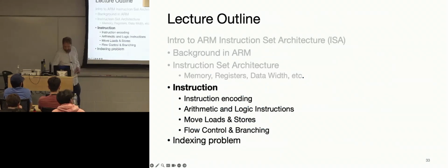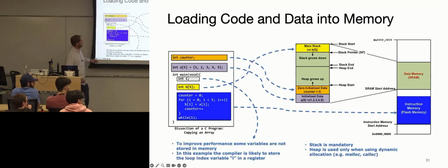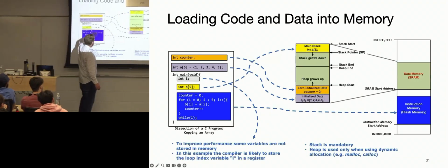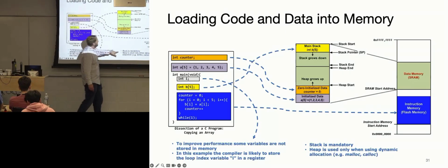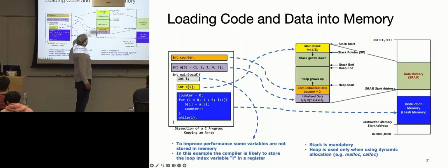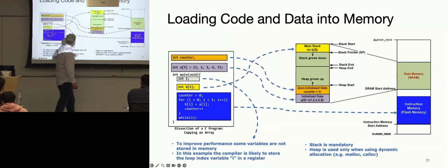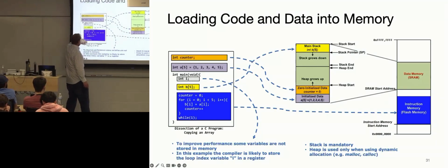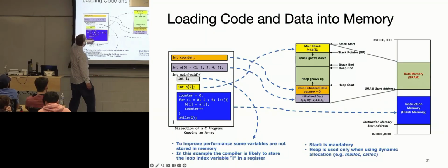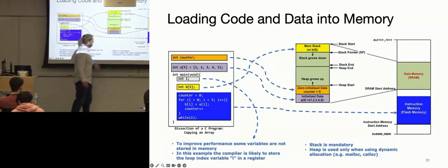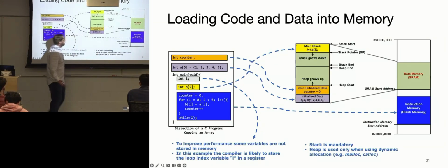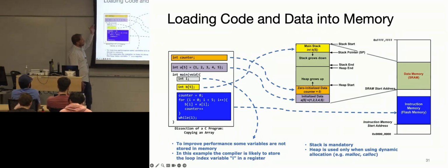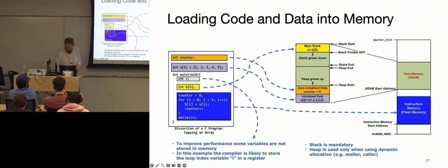All this slide was just showing you is that different types of data are stored in different locations. The thing to remember about the slide is the stack grows down. The stack is for things that are run at runtime. There's constants, which could be put on the heap. We don't generally use the heap in this class. You can use it, but we just don't teach it. It's just an extra piece of complication that's not that necessary. But we'll do a lot of stack work, and you just have to remember the stack grows down.